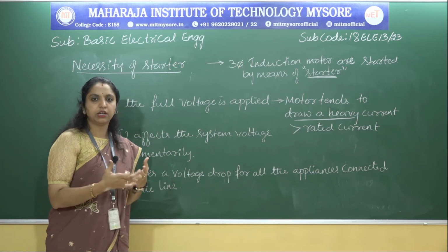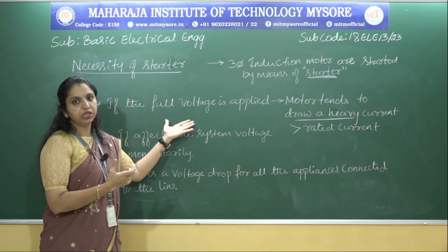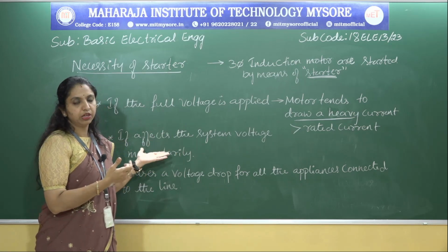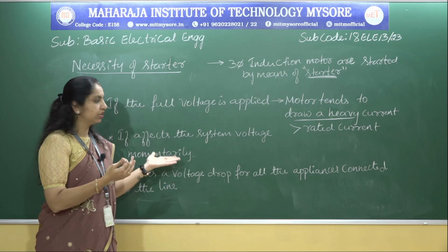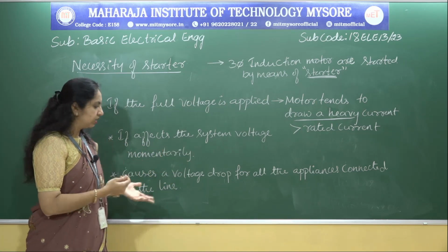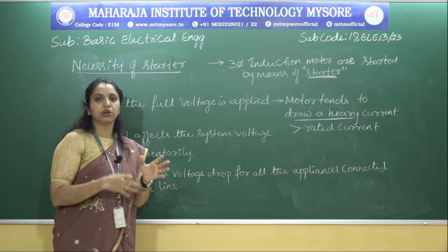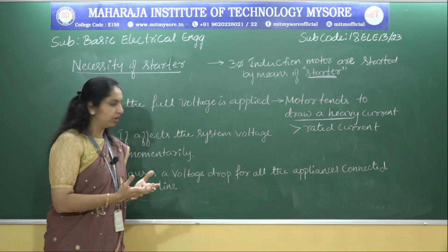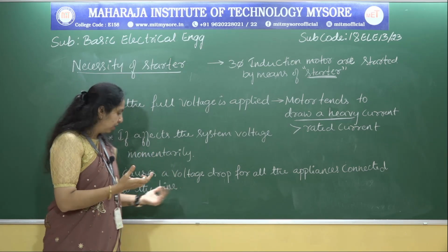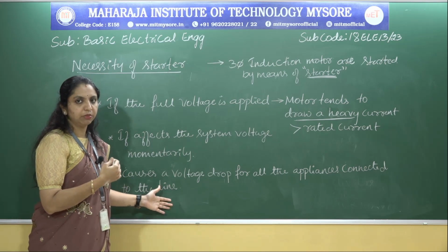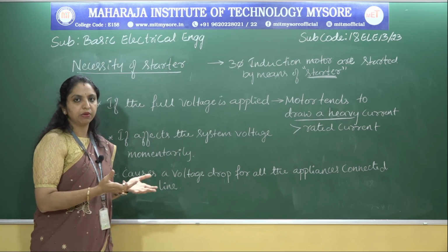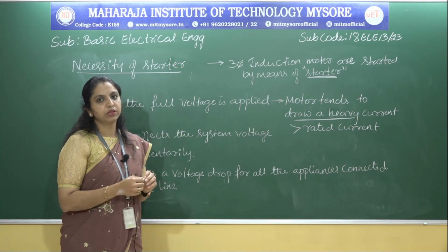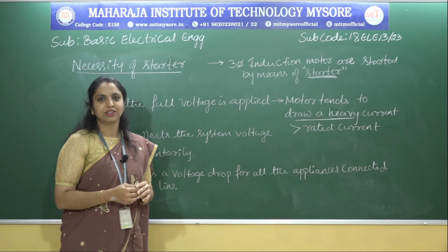So why is the starter required? Initially the motor tends to draw heavy current, which is dangerous, and it affects the system voltage momentarily, and damages the elements connected to the motor. There will be a voltage drop for all the appliances connected to the same line, which is not desirable. So to limit the starting current, 3-phase induction motors are started by means of a starter. This is all about the necessity of the starter.